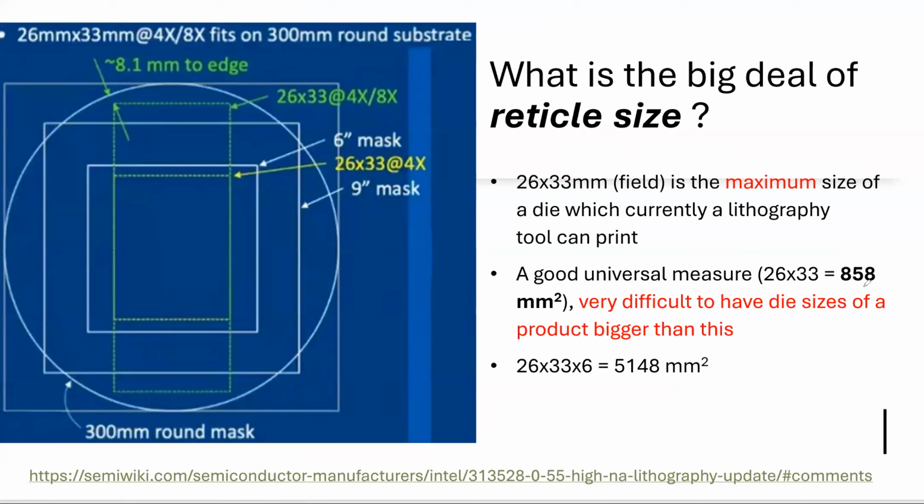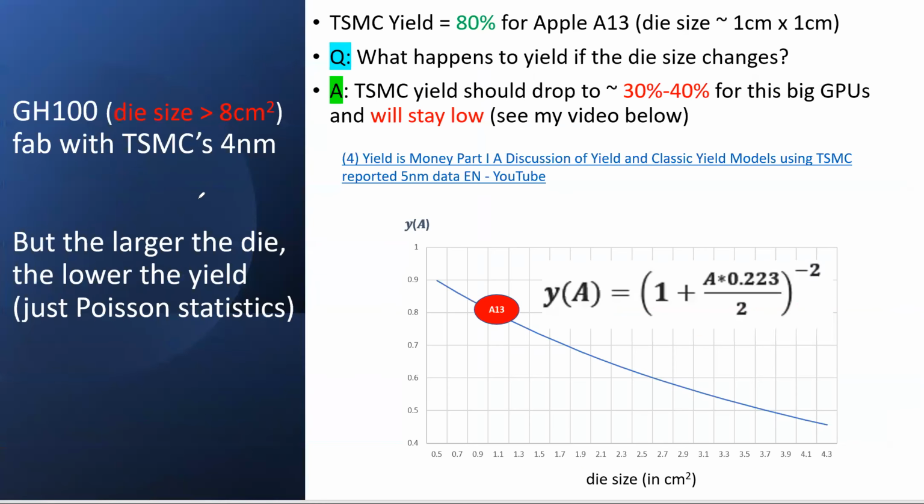You cannot do that much, right? You need at least some room around. So about 800 something, 820 is the maximum you can do. And then you can see that the die you make has a lower yield, so it costs a lot more. TSMC is the only one who could do such a big die with a reasonable yield, which is less than 50%, right?